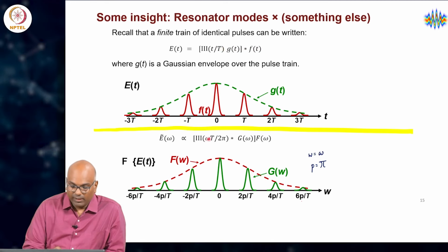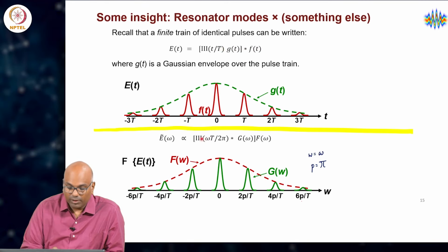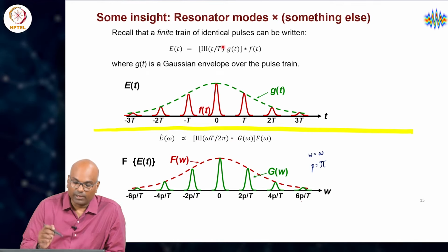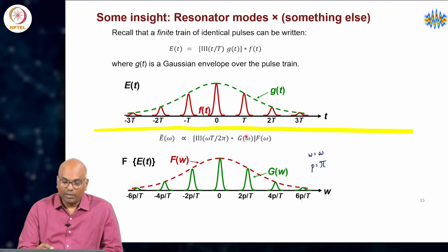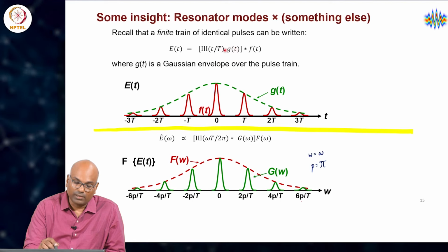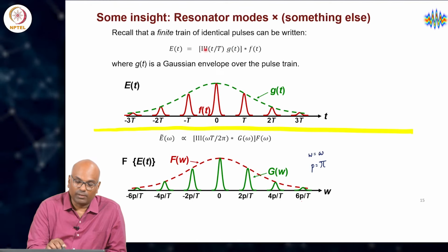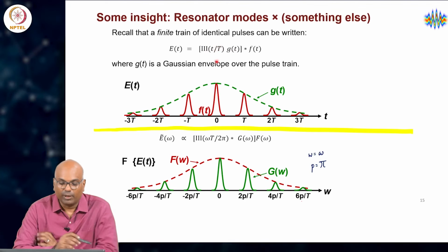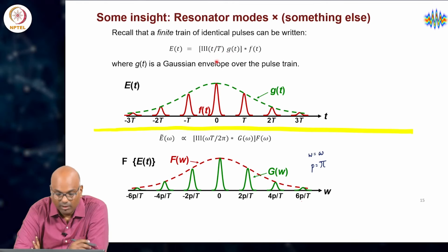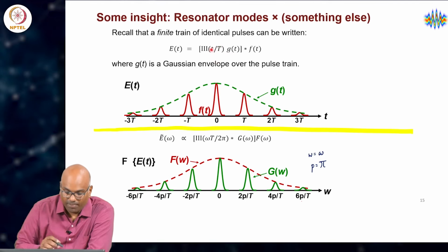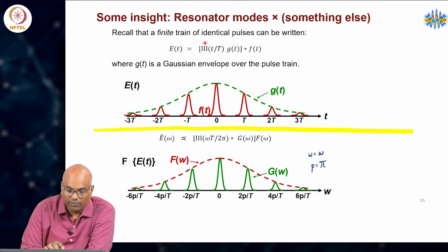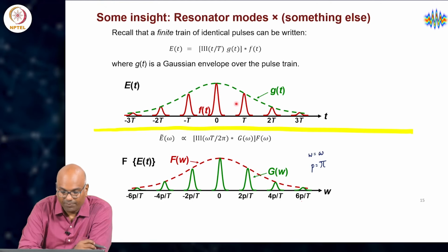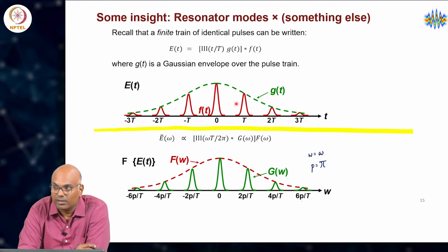Likewise, the convolution between the periodic function and g, when Fourier transformed, becomes a multiplicative product of the individual inverse Fourier transformed functions, little g, and we use the same symbol here for the periodic function, but in the time domain. T divided by the periodicity turns out to be t, which we know is the round trip time. So this is the form of the function in the time domain. It is almost like a mirror image, if you wish, between the two domains.